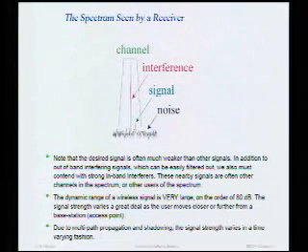Okay. The other issue that Al brought up was the dynamic range of the signals that we're receiving. You don't stand still and communicate, although there are point-to-point communication systems. Even in those situations, the signal strength varies. You might have to design a receiver that has to work over a few meters range to a few kilometers range. And that might mean a huge dynamic range in the signal that you're receiving. I put a number here, about 80 dB, let's say, for a cellular communication system. This signal varies not just because you move closer and further away from your transmitter/receiver, but also because the environment over which you communicate changes.